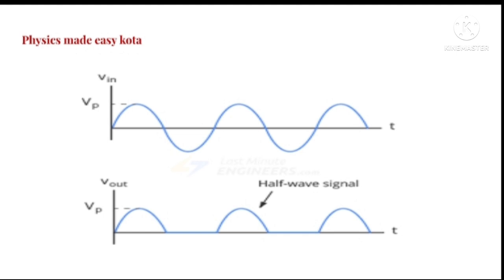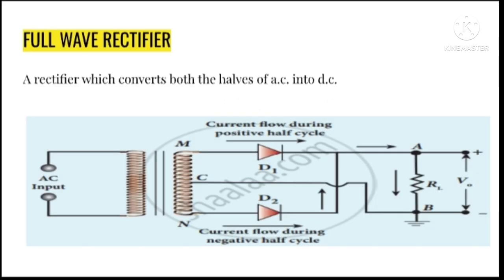There is no junction current for reverse biasing, and for that we get no output signal. Only when the diode behaves as forward biased is the output signal possible. As the efficiency of the half wave rectifier is low, now we are going to understand how to improve the efficiency by using the full wave rectifier.